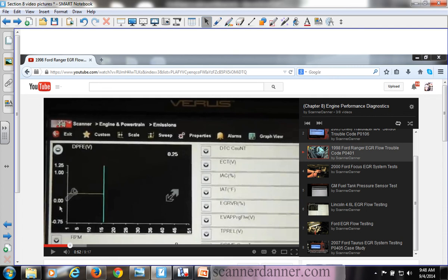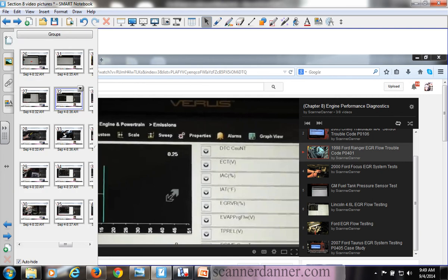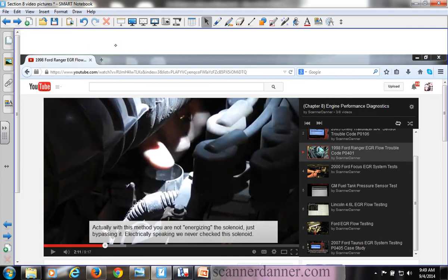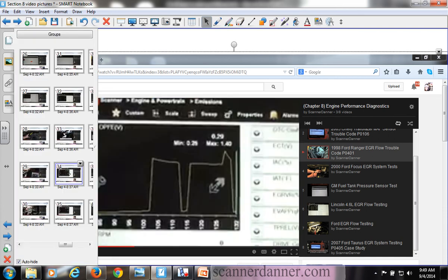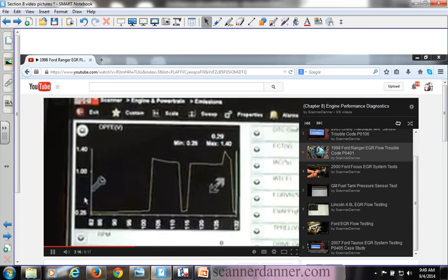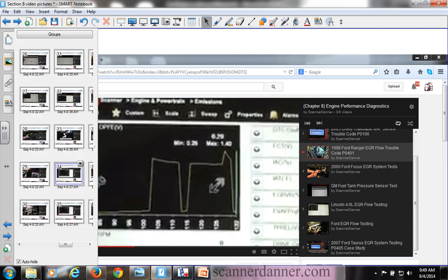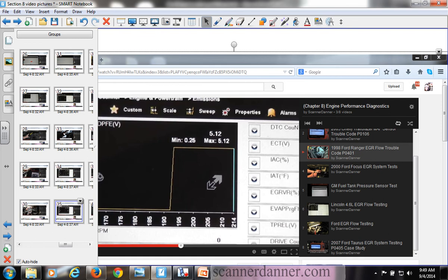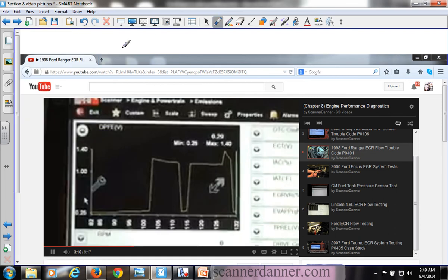What about this one? Well, voltage is low to begin with, so let's keep going. I do the same thing. Notice my finger's over the same vent solenoid again, or apply solenoid. I'm trying to force the valve to open, and I do that. I get some kind of change. This is blurry here. It says 0.25. I think I got a better shot of that. No, not really. 0.25 at this bottom line, right here. Goes up to like 1.3. It sits there, and this is as I'm taking it on and off. And by the way, the engine's pretty much stalling when I'm doing this.